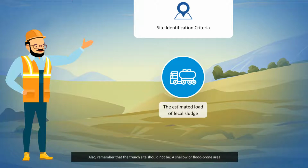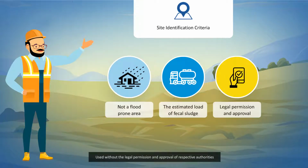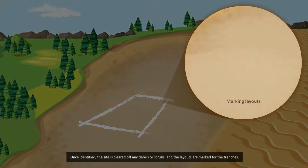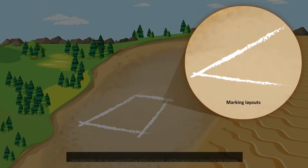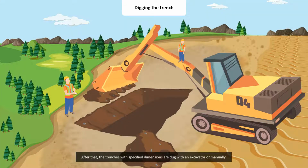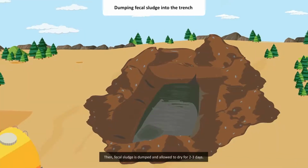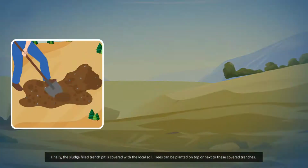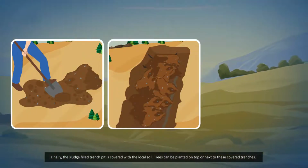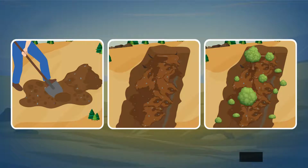Also, remember that the trench site should not be a shallow or flood-prone area, and should not be used without the legal permission and approval of respective authorities. Once identified, the site is cleared of any debris or scrubs, and the layouts are marked for the trenches. After that, the trenches with specified dimensions are dug with an excavator or manually. Then, fecal sludge is dumped and allowed to dry for 2 to 3 days. Finally, the sludge-filled trench pit is covered with the local soil. Trees can be planted on top or next to these covered trenches.